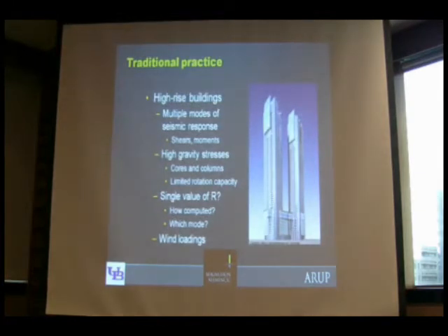So with high-rise buildings, we see some significant differences in terms of response compared to low-rise buildings. The design procedure that I introduced a few moments ago that represents traditional practice, where you compute a base shear and then you distribute that base shear over the height of the building using a first mode profile, might be appropriate for 2, 3, 4, 5-story buildings where one mode of response controls both the base shear